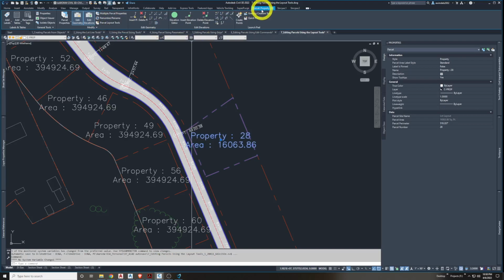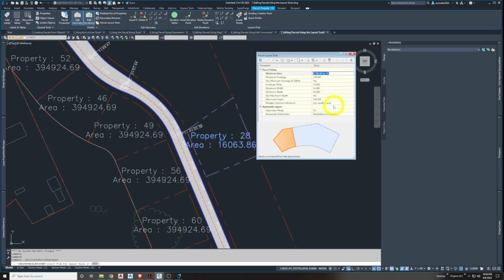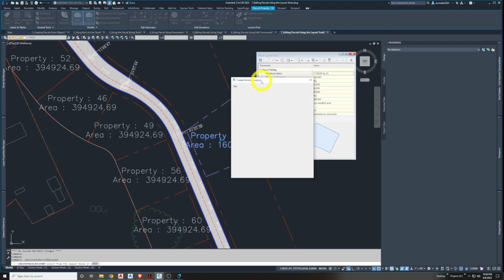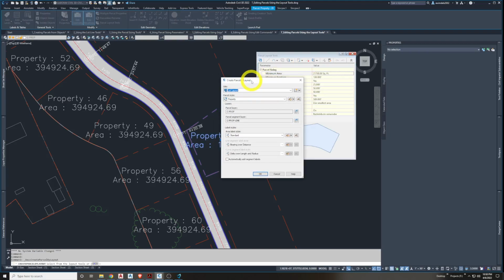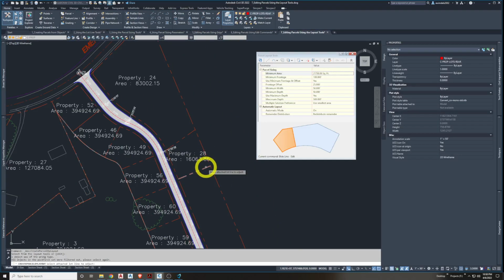Once my parcel's picked in the contextual ribbon, that's still set. Slide line edit. Okay, this is the right dialog box. I'll confirm that. We'll hit OK. It says when prompted, select an attached lot line to adjust.